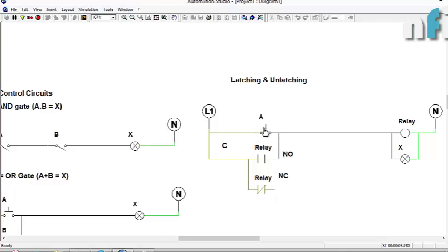Okay, so what happened here is when you press this switch. Now I'm just pressing it. This relay is on because this is giving supply of line and neutral here. And due to this relay, this contact is closed. All right. And when this contact is closed, now we have two supply. One is coming from here, another one is coming from here. It is going to this indicator relay. So even if I release this one, this will remain latched because of this auxiliary supply. So this NO contact is an auxiliary contact which is turning on a relay and providing some auxiliary supply of line.